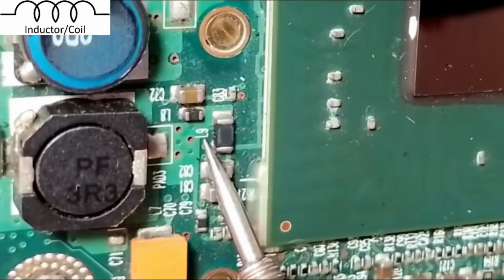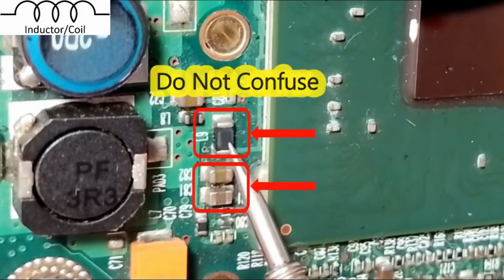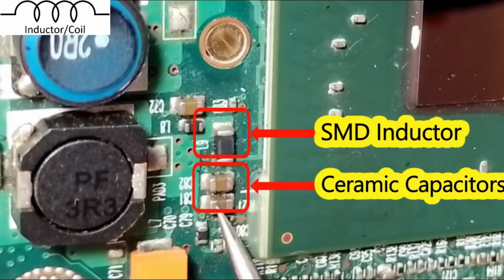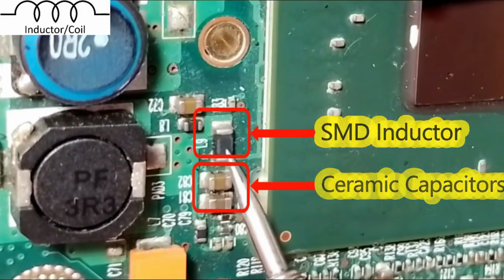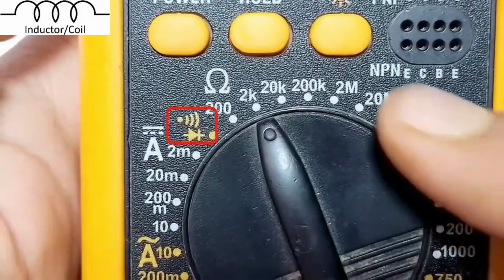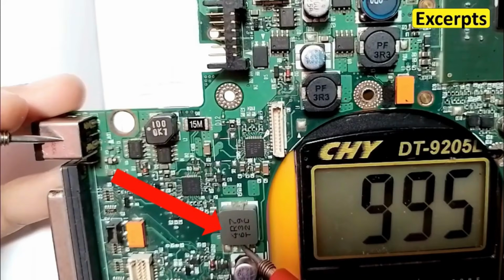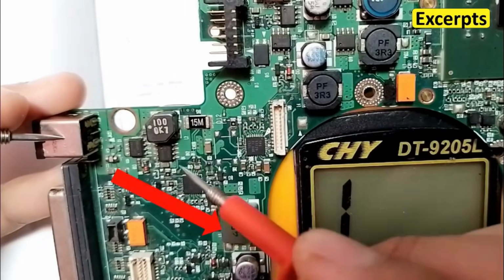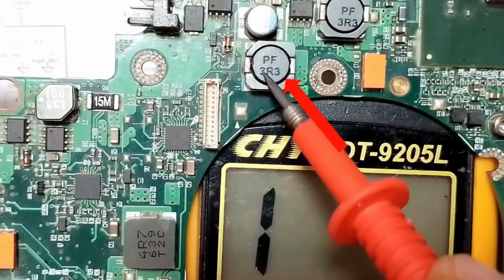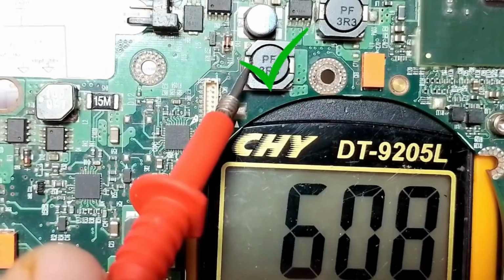Okay, so please pay attention. Do not confuse inductor and ceramic capacitor. As you can see, those are ceramic capacitors and this is an inductor. So let's first select the continuity option in the multimeter. Let's check the first inductor. We get a reading. Let's check the second one. We get a reading. Let's check the fourth inductor. We get a reading. Good.